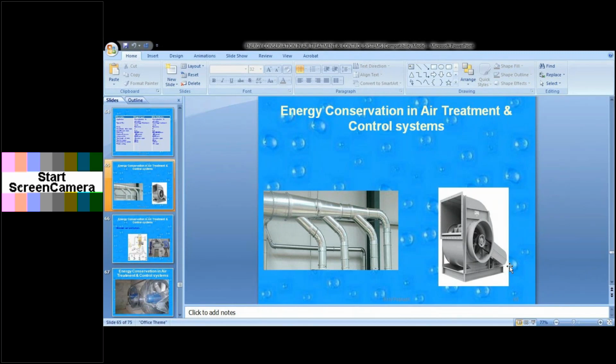So we calculate for this particular CMH or volume. You see the pressure drop and the dia. The dia is all fixed. We have a table-like chart arrangement, like a psychrometric chart; a pressure drop chart is there for these ducts. If you check based on that, if you redesign, because originally they would have added that particular extra volume also in the same duct.